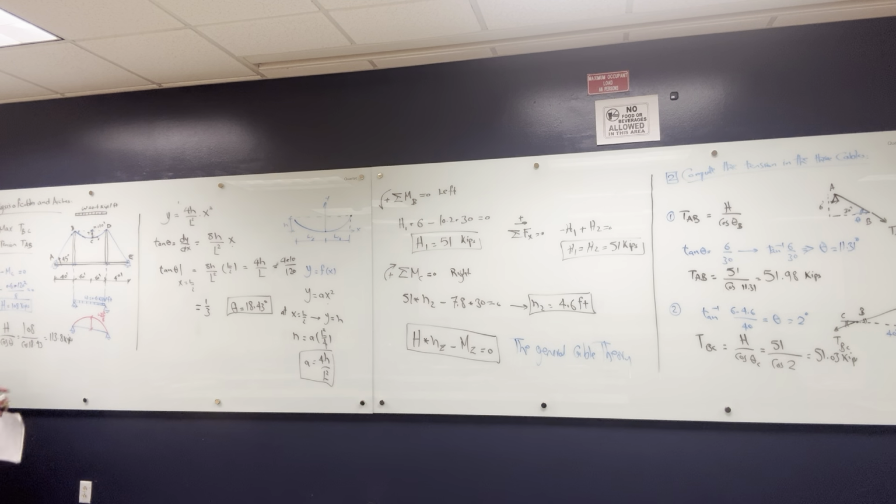Actually, the second tension, what he's asking here, tension AB, that's very, very simple. How? Right now I know the horizontal, and I know the angle. The angle is constant on this cable. It's 45 degrees. So the tension TAB is going to be the horizontal force over cosine theta. So the horizontal is 108, and I know cosine 45 degrees. And this is going to be 152.76 kips. That one was much easier.